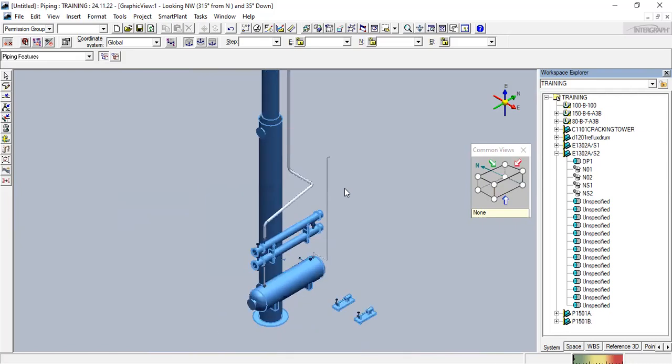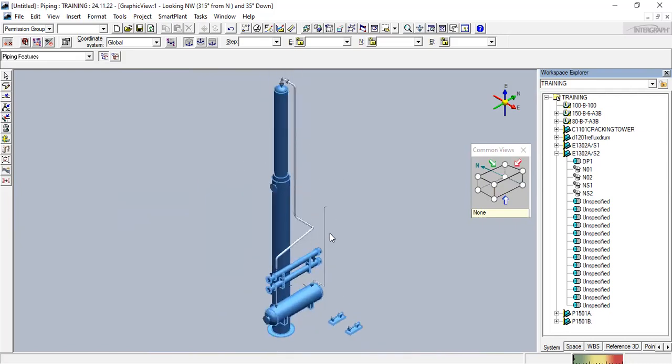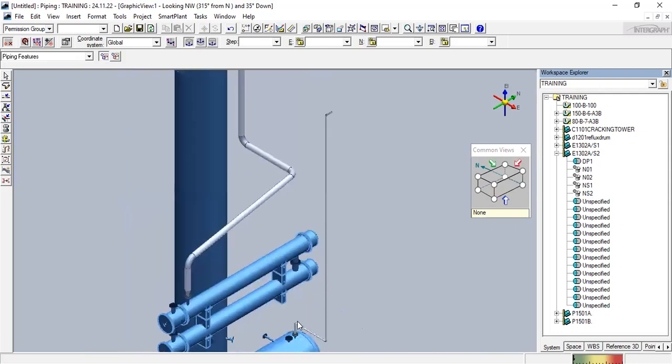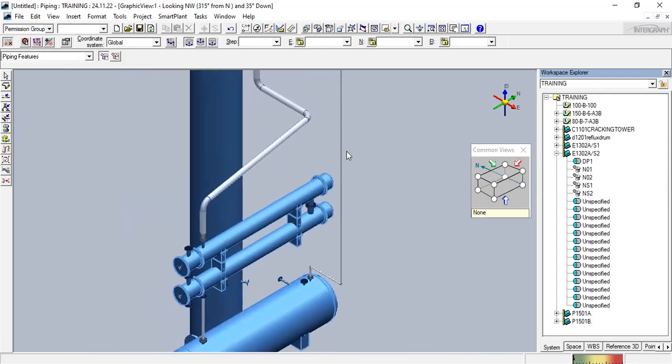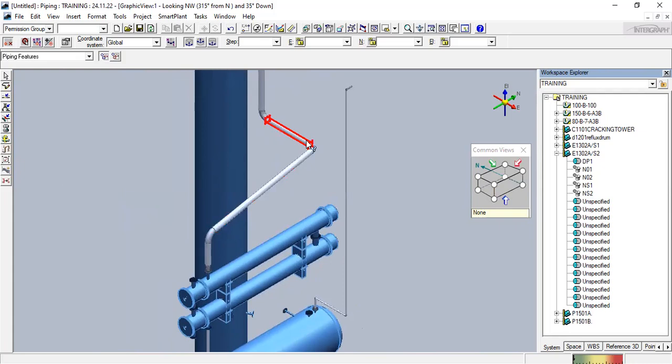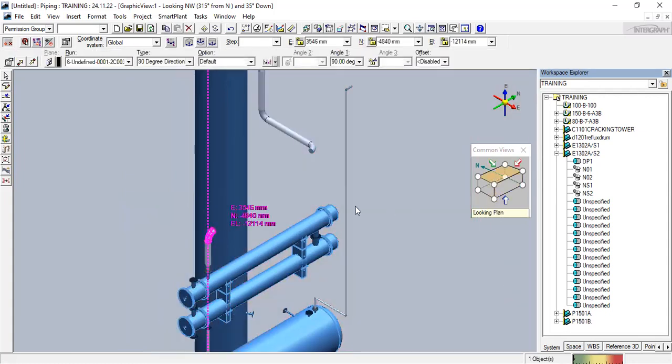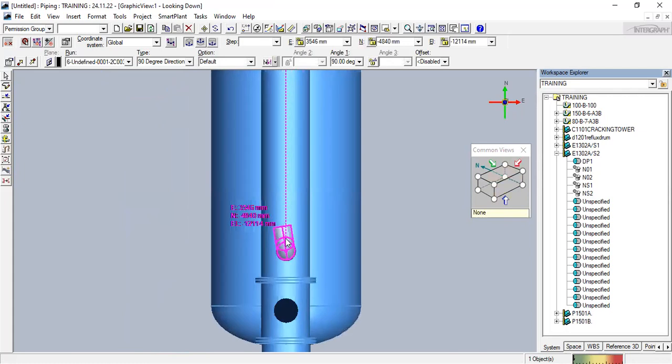In a live project, you have many things, like some structure will be there, support from the support point of view. Okay, so accordingly you have to route. I need to modify this line. First delete it. Okay, from the top view, see the angle of your elbow has changed.